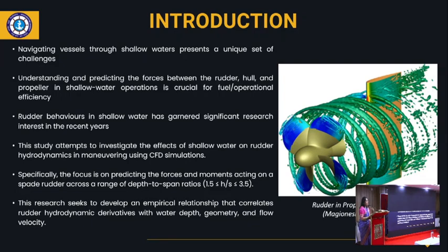So I would just come to a conclusion of this slide, saying that this is the status of the present research in the area. Though there have been a lot of contributions from various contributors, starting from Kijima in the year 1972 to contributions as late as 23 and 24, and a lot of consideration for the rudder aspect, an equation or prediction which Kijima otherwise gives as a correction for the hull in shallow waters is missing for rudder and propellers. But the rudder has a bigger contribution to the maneuverability of the vessel.